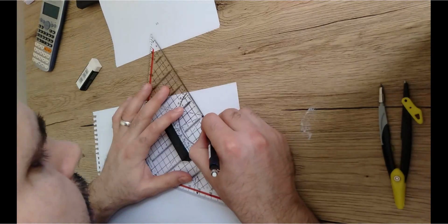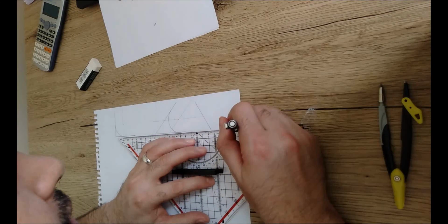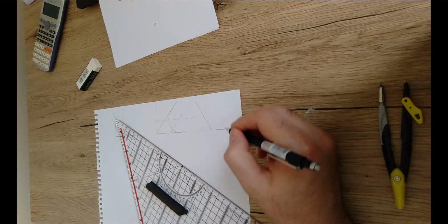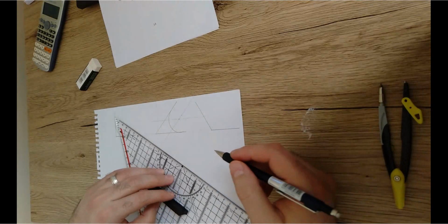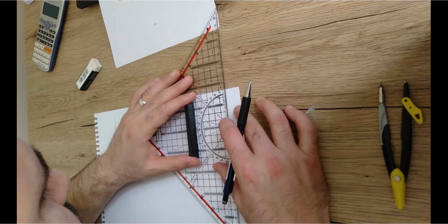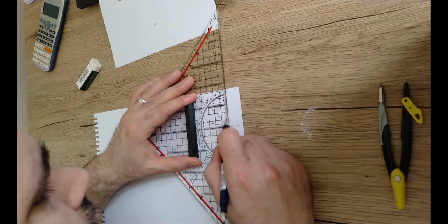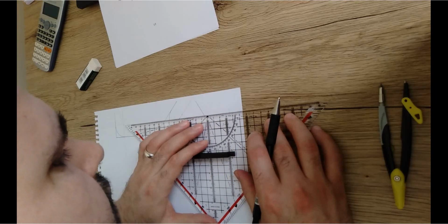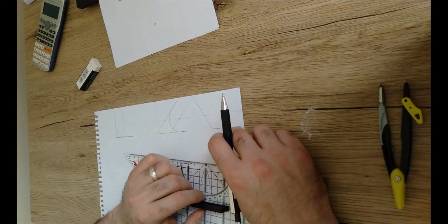So this should be the second line. So I do have here one line, which is this one, and there is another line which should be this line. All right, then I have to set up a curve between them that is tangent to both. So I have to draw two lines. One is parallel to the horizontal line, one is parallel to the inclined line. The one that is parallel to the vertical line, no problem, it is easy. We can easily draw this one. If you just draw a very light line normal, then measure 20 millimeters and mark a point, then from this point you can easily draw a line that is horizontal to be parallel to the first horizontal line.